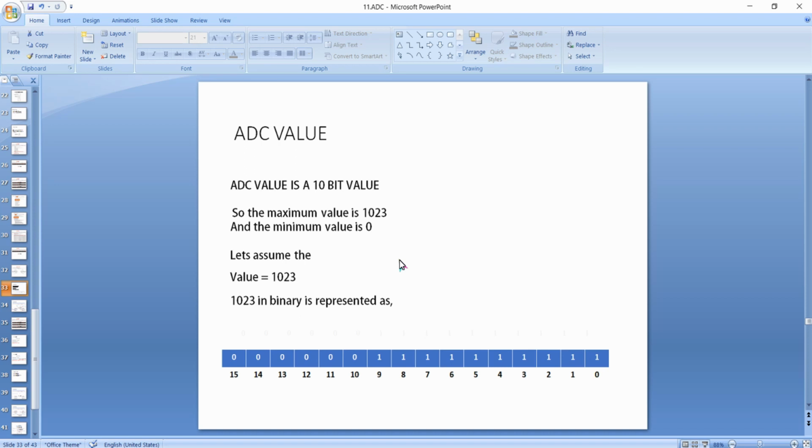So this is how the ADC peripheral available in the microcontroller provides us with the step values corresponding to the voltage provided in the particular ADC channel. And if you are operating the microcontroller with a 3.3 volt signal, I will be getting this 1023 step value for the provided 3.3 volt signal in the analog channel of the microcontroller.